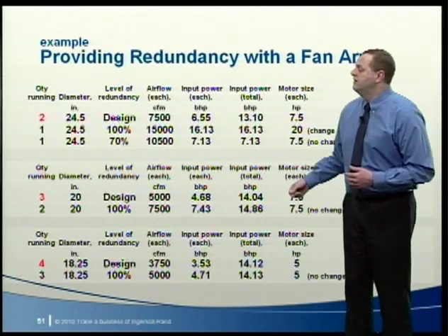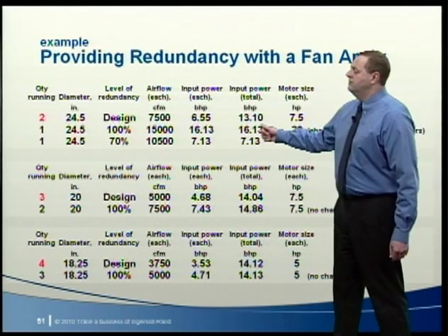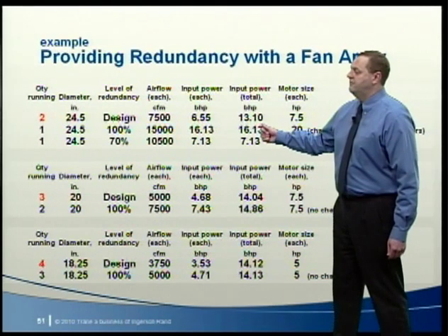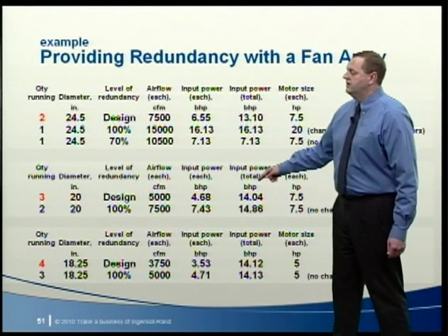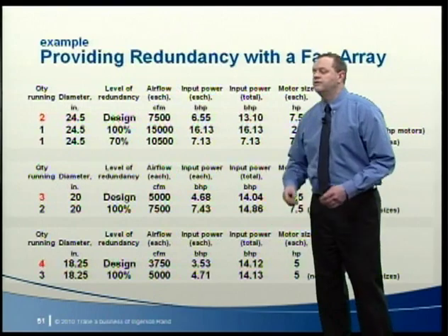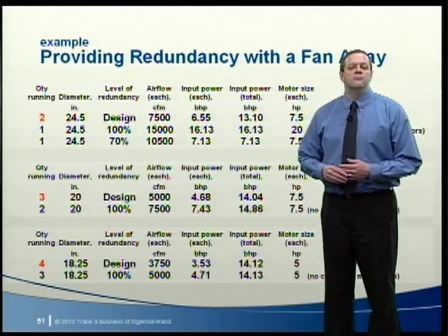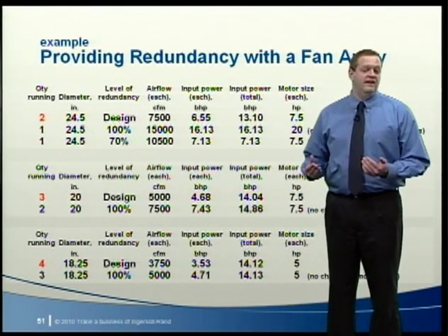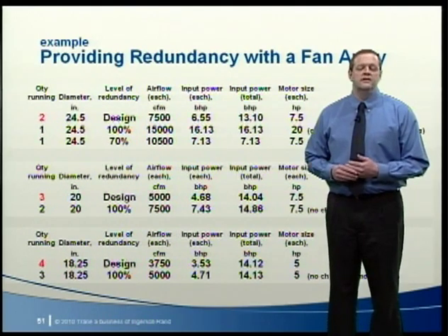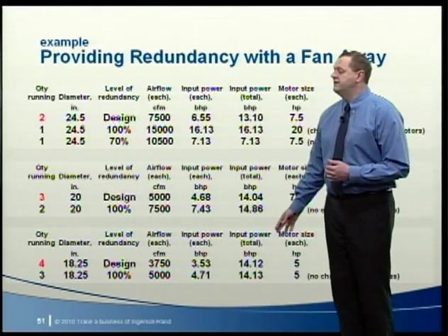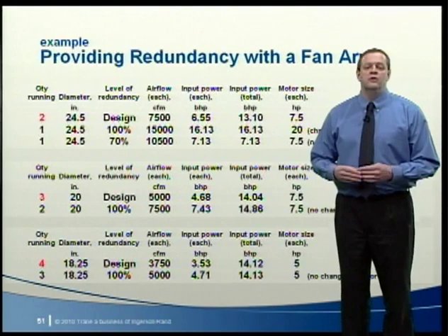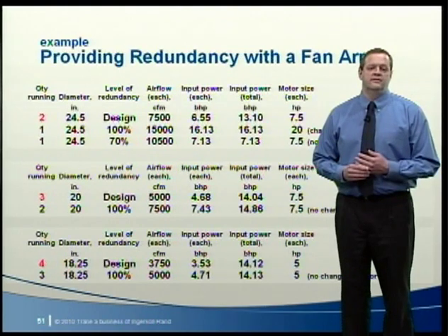The 2-fan array requires the lowest total input power when all fans are operating, 13.1 compared to over 14 for the 3 or 4-fan arrays. But it does require equipping each fan with a larger motor. Either the 3 or the 4-fan arrays can provide 100% redundancy without changing the motor size.